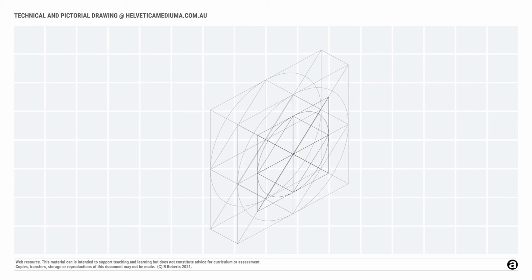If your drawing calls for a hub or an inside to the wheel, use the same principle, draw a new square in a concentric way. So coming out from the center point, I've drawn another square, diagonals and the diamond, and used that to form an ellipse in the middle. Then extend back to the left, back inside the wheel, the distance that you need your hub to move into the wheel. After you've done that, draw another square and form up another ellipse.